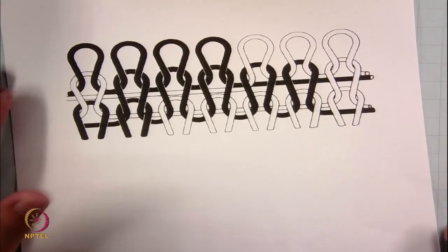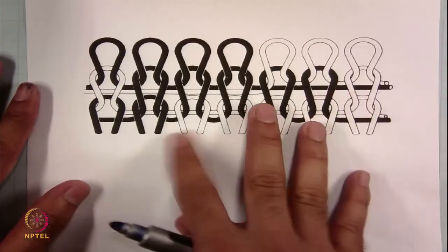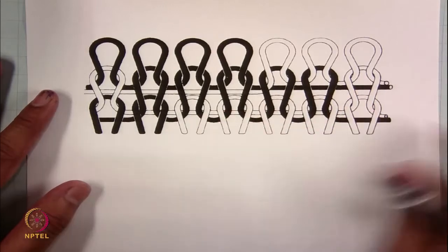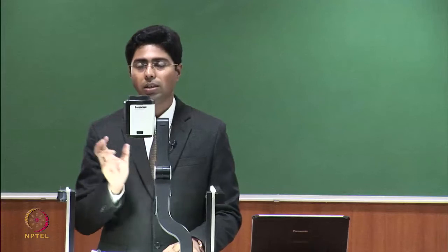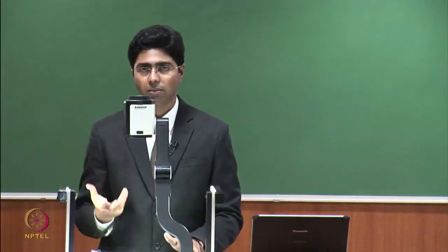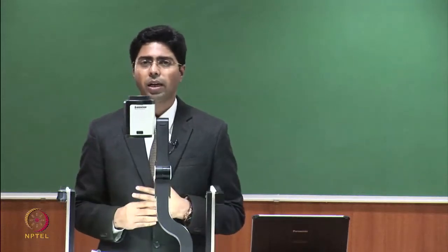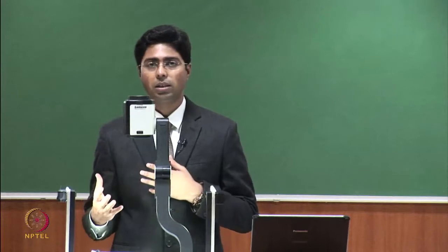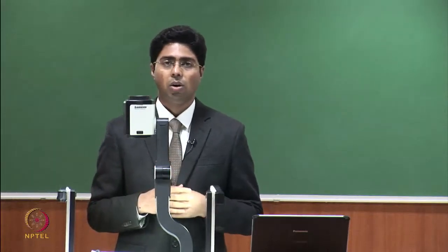So, this is usually used in jacquard type of knit fabrics. In jacquard fabrics, in the same course some needles will be catching yarn number A, and some needles will be catching yarn number B. In one of the lectures I gave you a demonstration on interlock machines, where even feeders were caught by the cylinder long butt needles and odd feeders were caught by the cylinder short butt needles.